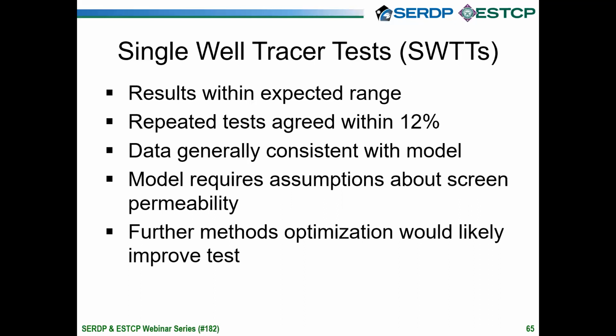But I would like to note that the interpretation model does require some assumptions about screen permeability and well construction that can't be directly measured. So there is some unresolvable uncertainty and potential for bias with the technique. Also, because we felt these tests were largely successful, we think there's value in additional work. Further optimization could probably improve the performance of this method.